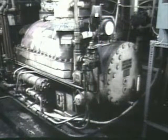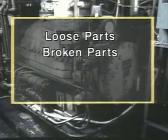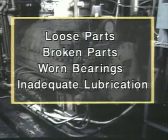Other possible causes of cooling water flow problems include cooling water valves being out of position and cooling water pumps not operating properly. Air binding in the water side of the condenser or in the cooling water system could also reduce the condensing rate. Compressor malfunctions can cause problems in a refrigeration system. Typical causes of compressor problems include loose or broken parts, worn bearings, and inadequate lubrication.